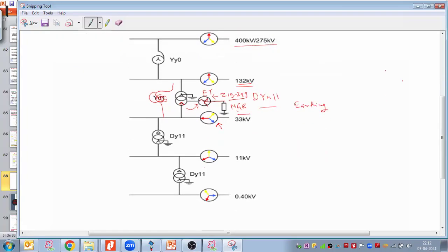Now they have another voltage range which is 33 by 11 kV. In that voltage range, they use Dy11 again. Here again, Y and D1 means they are not indicating the neutral, they are just telling about the HV and LV vector configurations. Due to that reason, N is not coming in this complete snapshot. About the vector configurations only we discuss. So Dy and 11 again.